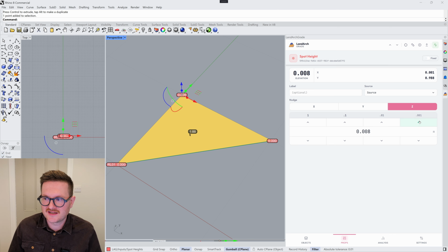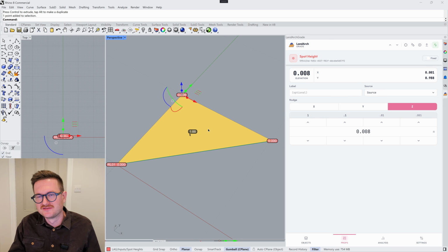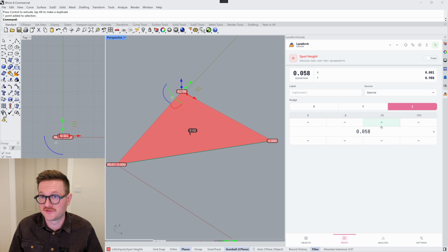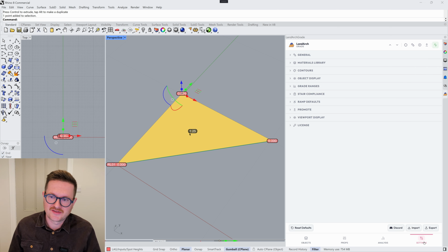If we bring it down a little bit to 1 in 88, that's, to me, still fairly acceptable, but it's getting up there in the too flat zone. Additionally, if you go up too steep, to 1 in 12, that's too steep, and so on. These settings are all user customizable.